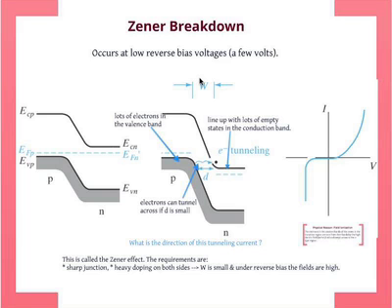Then the voltage, so if you look at the junction, that's our boundary. Let's say that's the transition region. That's W. Of course, these are heavily doped, so there's pretty much no voltage drop there. We assume it's a perfect conductor. We know from last class that this is not actually true. It needs to have some field, but for the sake of argument, that's very small. The field that gets applied here, which of course is in this direction, with charges here, charges here, balanced, is determined by the applied voltage divided by W. Pretty much.